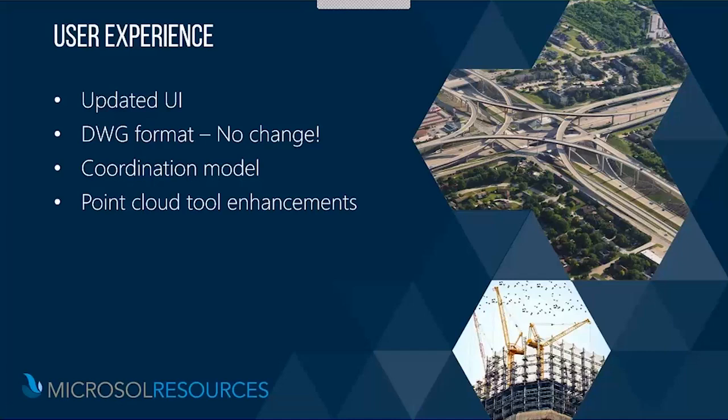A couple of minor things, such as the gallery view system variable. For instance, if you're inserting a block, and I'll be sure to show you this, and you click on the drop-down, you'll see that you can either have a list format or a gallery view, which is a thumbnail of what your block represents. Those sorts of things have been modified. And then last but not least, the UI Finder, which I'll give an opportunity to show you: if you're learning Civil 3D or you're not really experienced with it, the UI Finder helps you locate tools by just dropping a big red-orange arrow where the tool is on the Civil 3D interface.